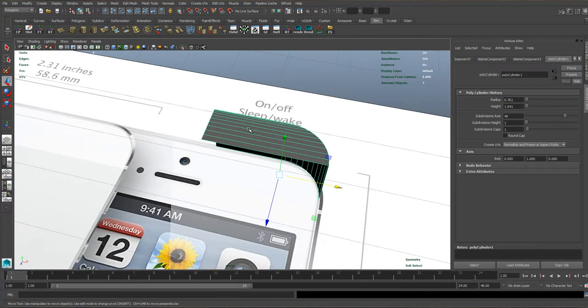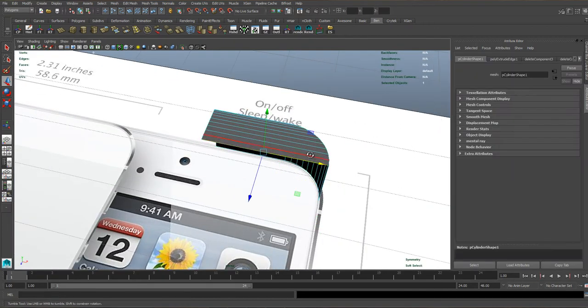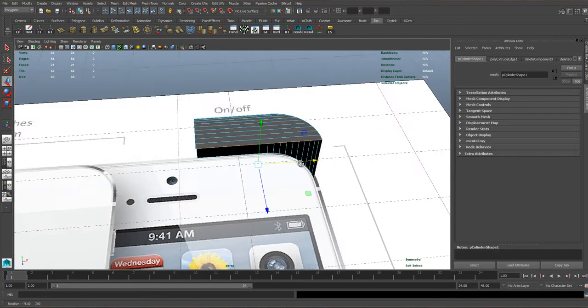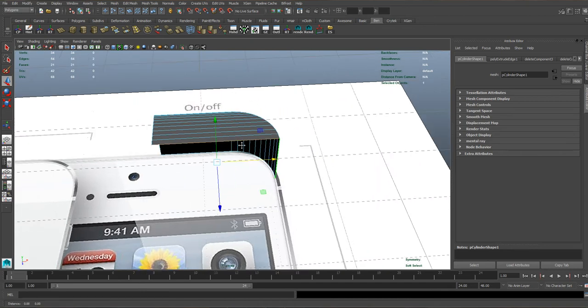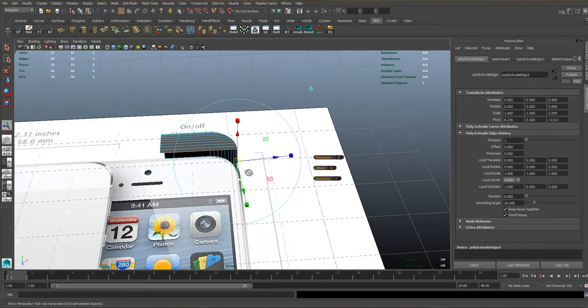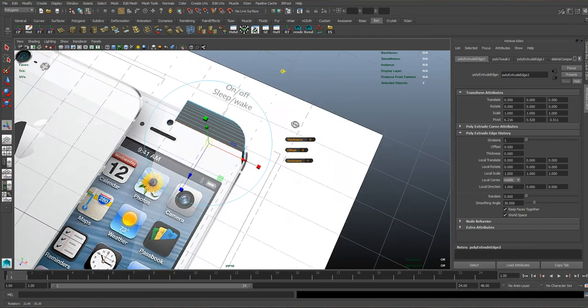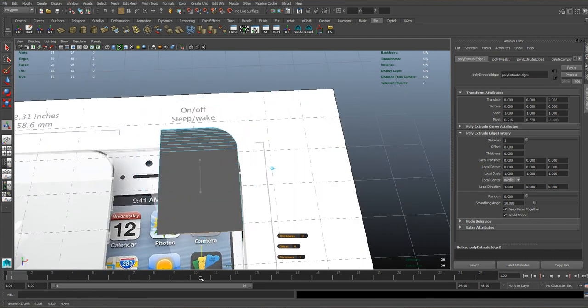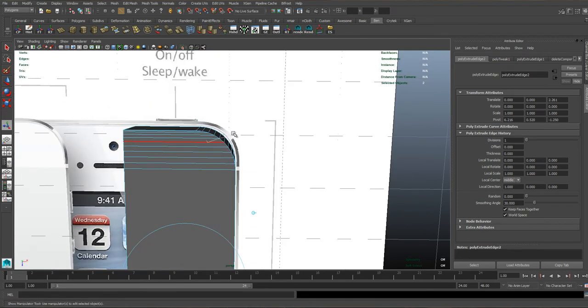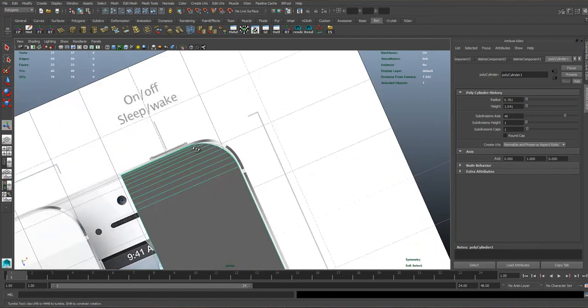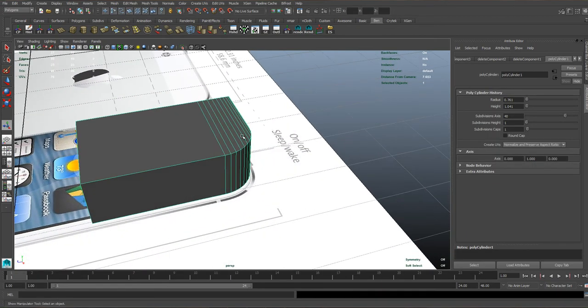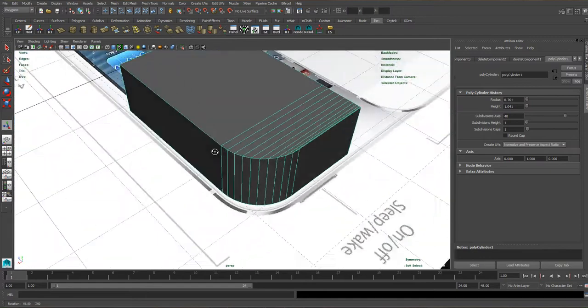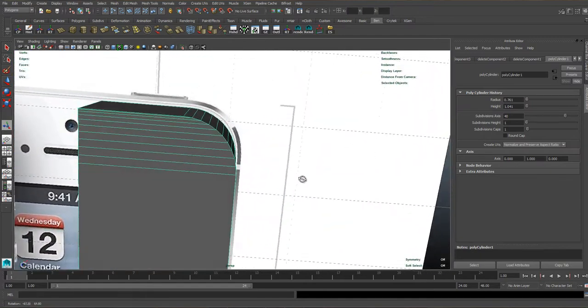Okay, next go back to 3D view, and obviously to jump about views you hit the space bar. Go to Edge, select only the bottom edges, so it's just these two big edges here that I'm selecting, and I'll extrude down. Again, I'll click on the little Snap to Grid button and move them down to there. And before we do anything else to this geometry, I'm going to create that metal outer edge there, and I'm going to use the geometry that we already have to do this.